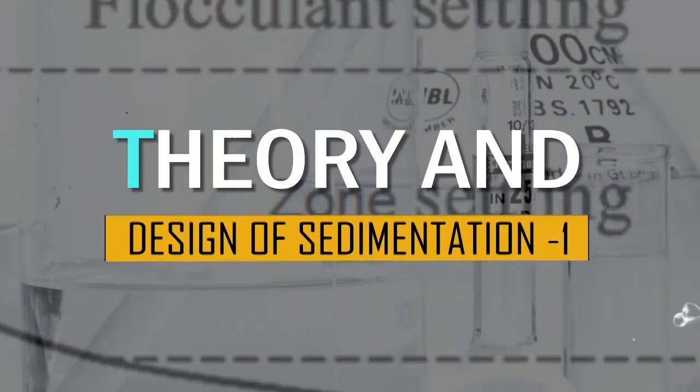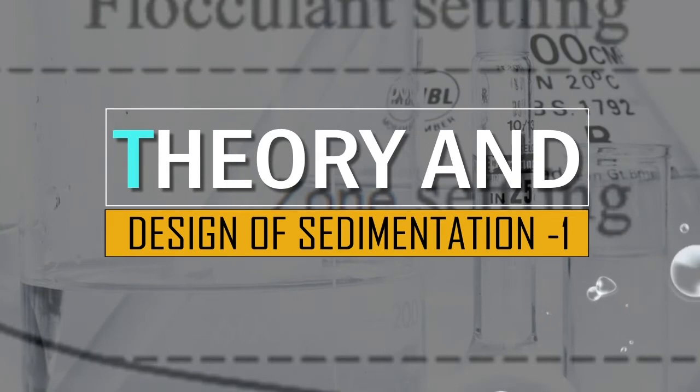Today I am taking a lecture on theory and design of sedimentation, part 1. Sedimentation is a physical water treatment process using gravity to remove suspended solids. Solid particles entrained by the turbulence of moving water may be removed naturally by sedimentation in still water. Settling basins are constructed for the purpose of removing entrained solids by sedimentation.